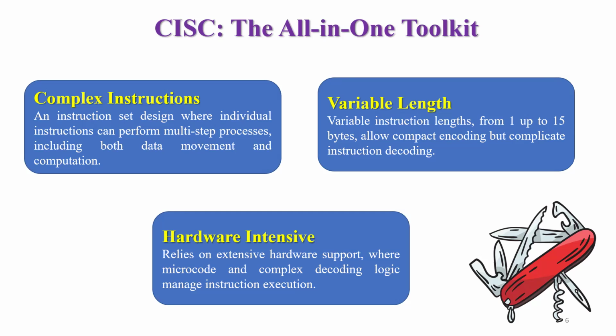Now, when we do talk about these CISC instructions, they are like an all-in-one toolkit. They can perform multi-step processes in one instruction. They are variable in length, which makes code smaller, but decoding harder. And the reliance on hardware and microcode makes the CPU more complex but powerful.